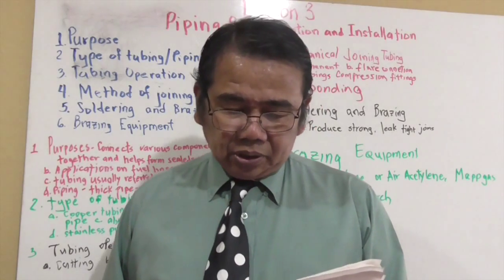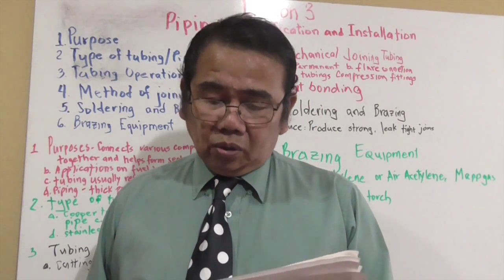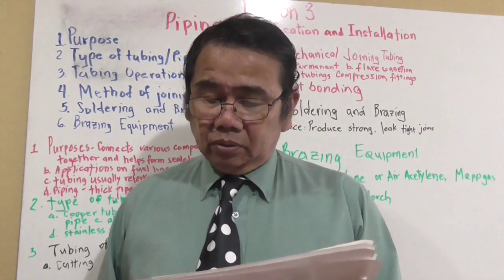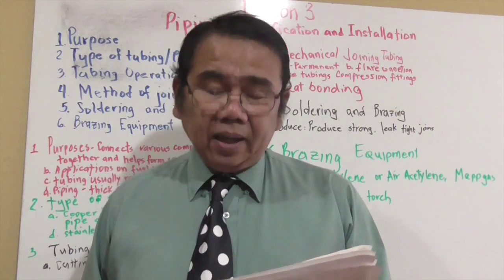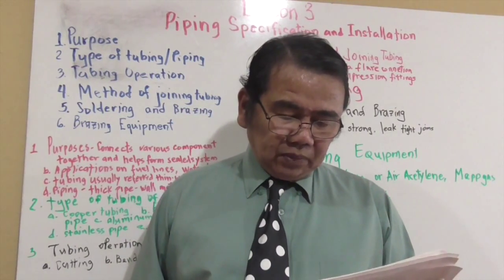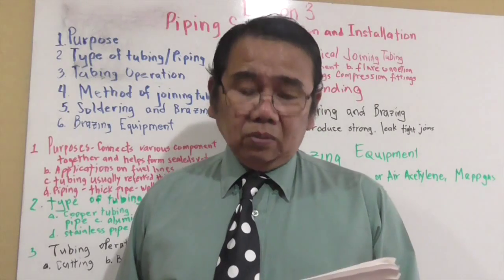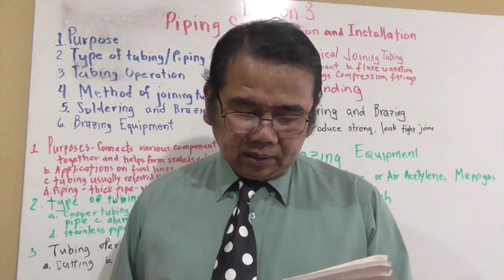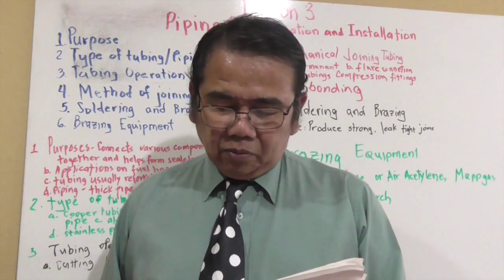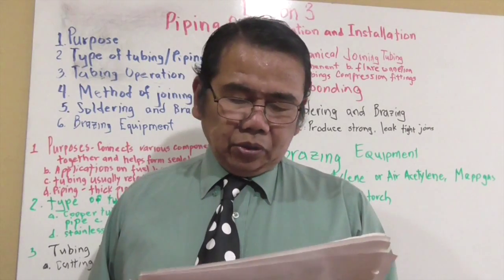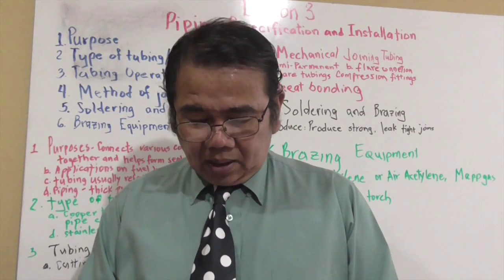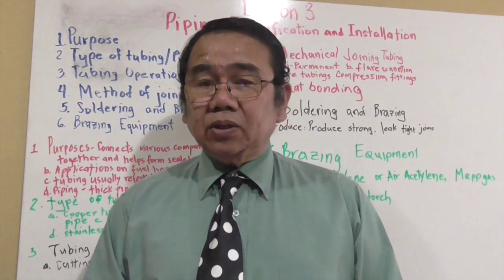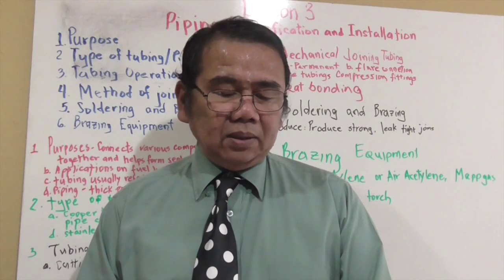Apply a wet brush or swab to the joint to crack and wash off the flux. All flux must be removed before inspection and pressure testing. Use a wire brush if necessary. That means you gotta clean the flux.